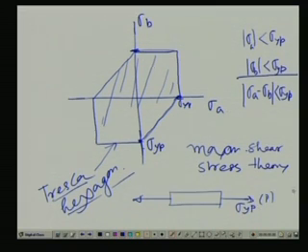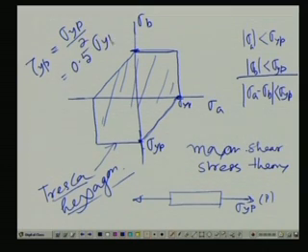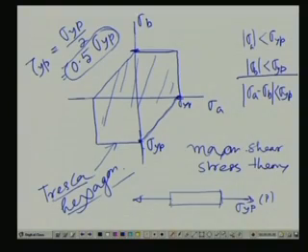So, by this theory, what is being predicted is that tau yield point should be sigma yield point by 2, that is, 0.5 sigma yield point. It is not exact, but it is quite close to the experiment. Well, we have other theories which we can continue in the next class. Thank you.